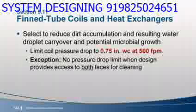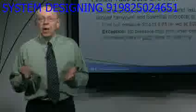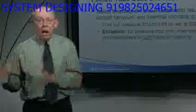There are no standards to define the relative ease of cleaning for differing coil geometries, but it's easier to clean a coil from one side if its geometry, in terms of number of rows and fin spacing, results in a 0.75 inch or less pressure drop. Coils with higher pressure drops can be used too if access for cleaning is provided both upstream and downstream of the coil.